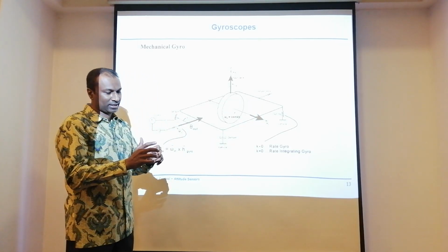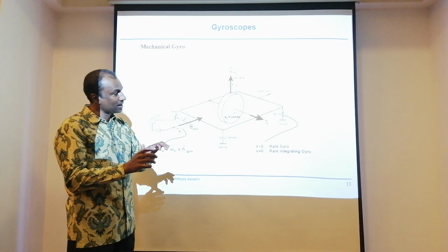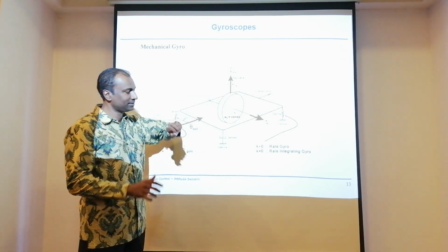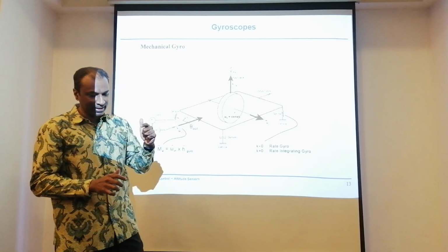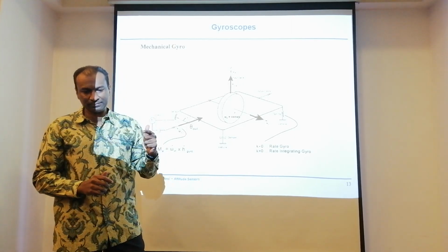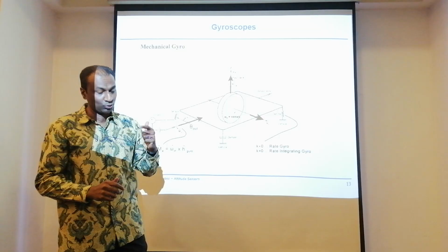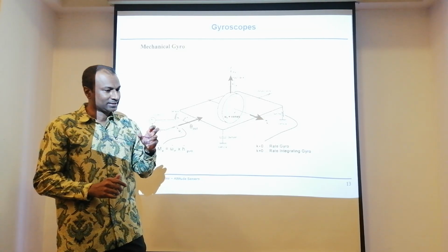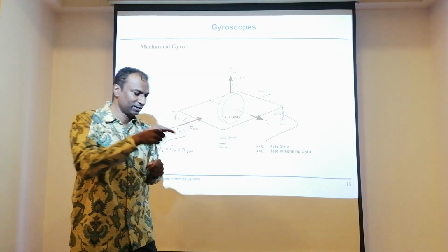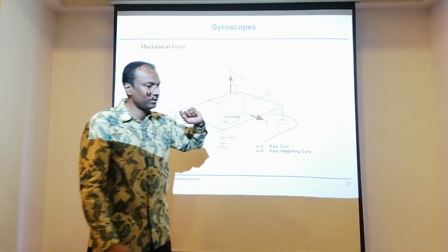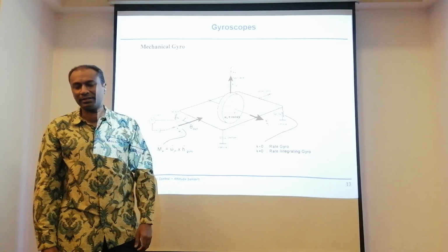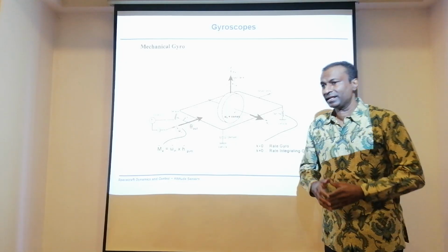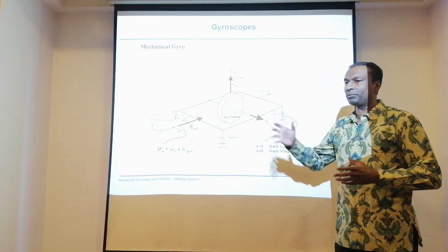So as you can see, you embark the mechanical gyro on the Z axis to experience the exact disturbance torque along that particular axis, but the exact deviation that you have is on the perpendicular axis. So that's how the mechanical gyro works. But then we can escalate the mechanical gyro through the fiber optics gyro.